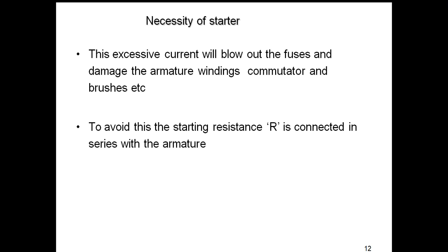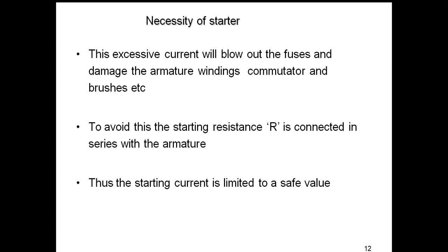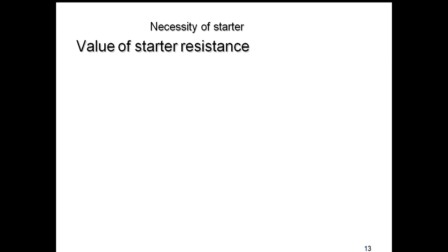And to avoid this, we introduce a starting resistance, represent it as capital R, which is connected in series with the armature, and this resistance limits the starting current to a safe value.